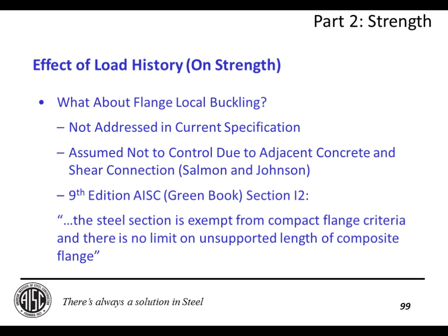What about flange local buckling? This isn't addressed in the current spec. It's assumed not to control because that top flange is tied into the concrete slab with steel anchors. Way back in the beloved 9th edition ASD book, it was addressed. We said that the steel section is exempt from compact flange criteria and that there is no limit on unsupported length of the composite flange. So that's still the advice that I go by. It's just not a problem for composite members.